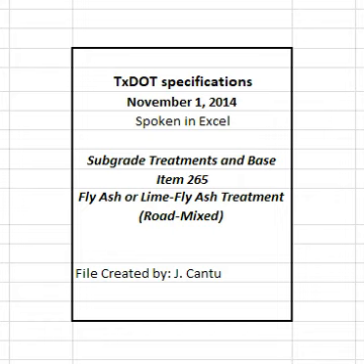4.3.1.2 Slurry placement. Provide slurry free of objectionable materials, at or above the approved minimum dry solids content, and with a uniform consistency that will allow ease of handling and uniform application. Deliver commercial lime slurry to the job site or prepare lime slurry at the job site or other approved location by using hydrated lime or quicklime, as specified.